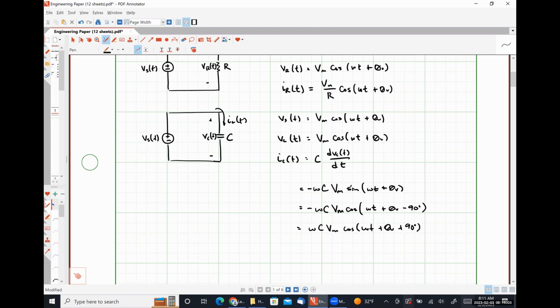That sinusoid will have the same frequency, right? So in all cases, we saw that for the capacitor, the resistor, and obviously for an inductor as well, our frequency of oscillations here is still omega, but our amplitude can be different and our phase angle can wind up being different. But we're going to have an excitation at that particular frequency, okay? So with that understanding,